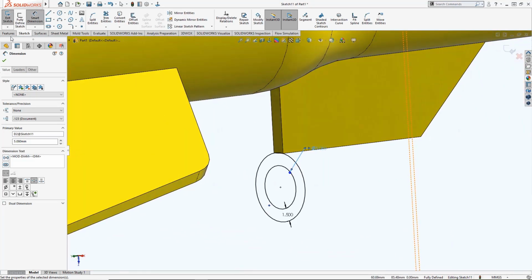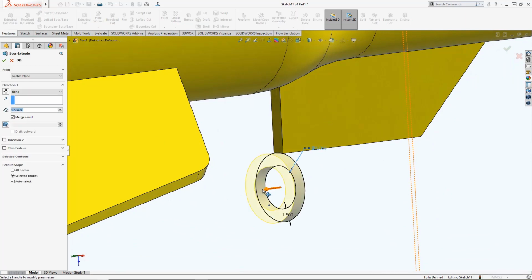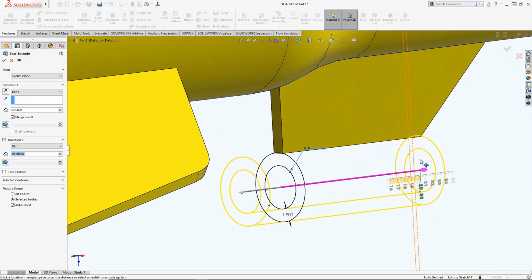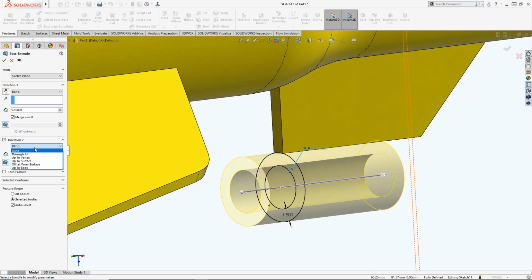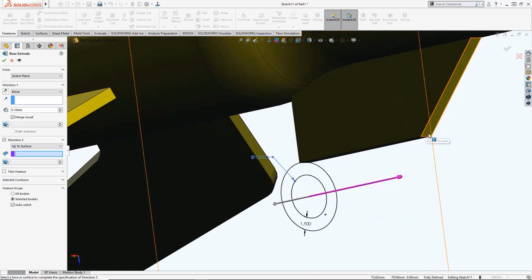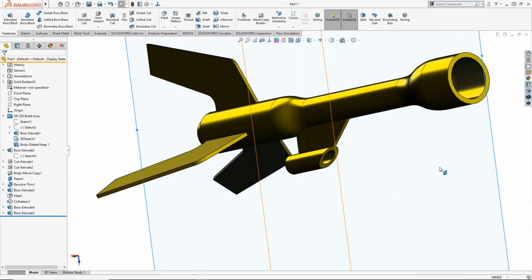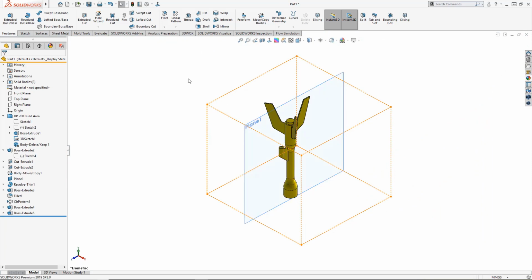Now extruding this particular piece out, I want it to be long enough. We'll see how this works in the launch. But again, I don't want support material. And if I use a horizontal face there, I'm going to have that happen. So let's just do an up to surface end condition. We'll map that topology. Then everything looks good.